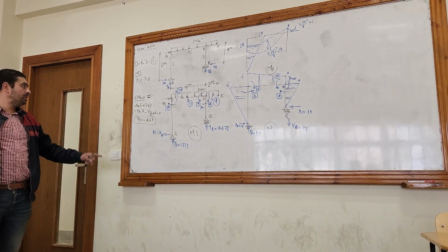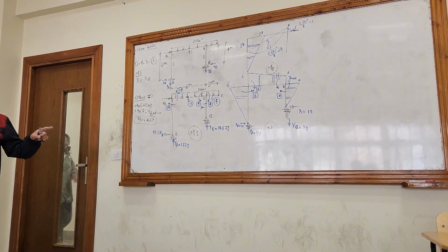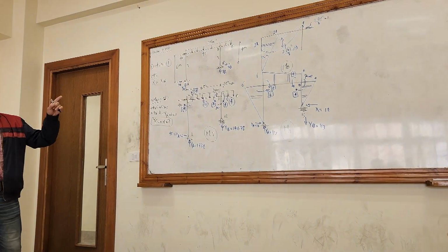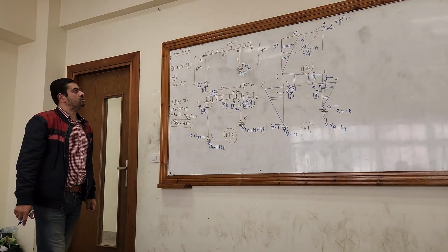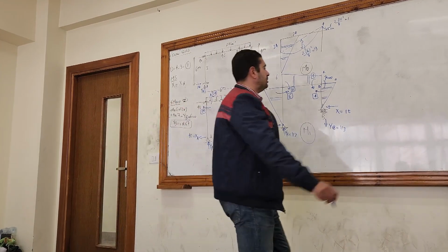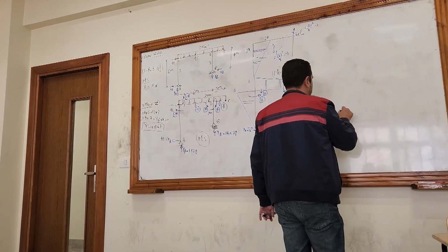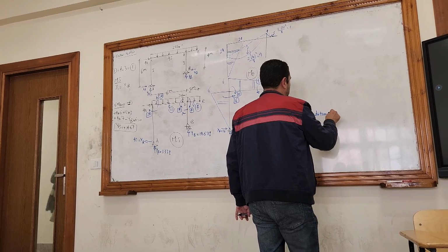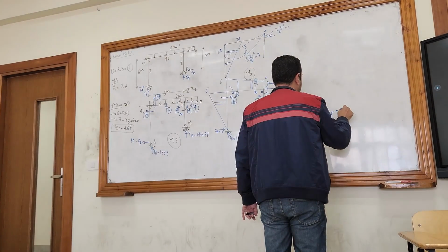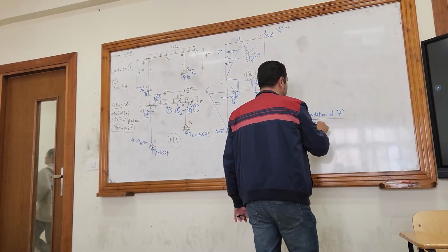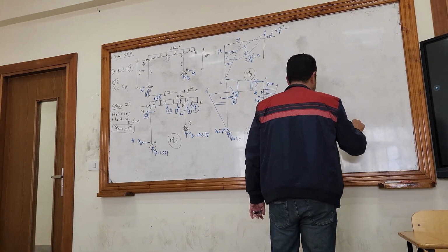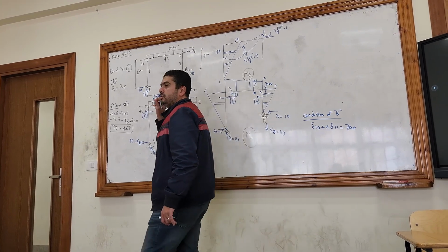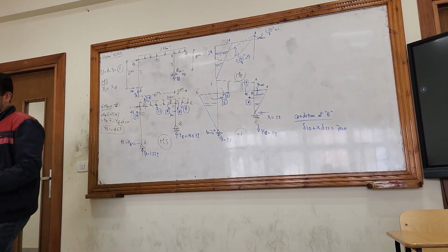The condition would be at the point that you remove the reaction at. I removed the reaction at point B, right? So the condition will be at B: delta 1 node plus x delta 1 equals 0. This point is not allowed to move horizontally. Okay?